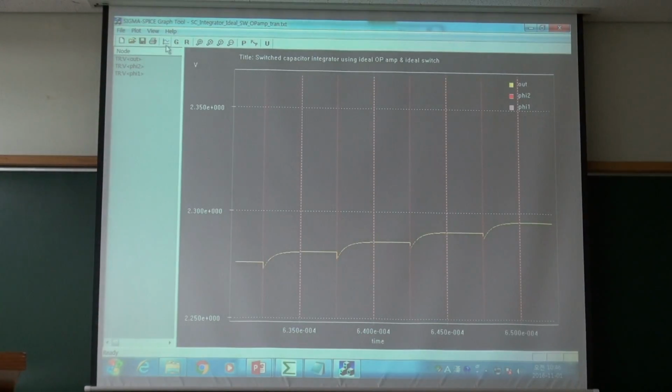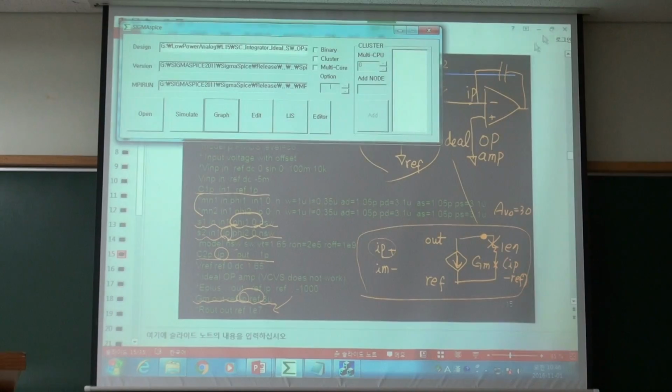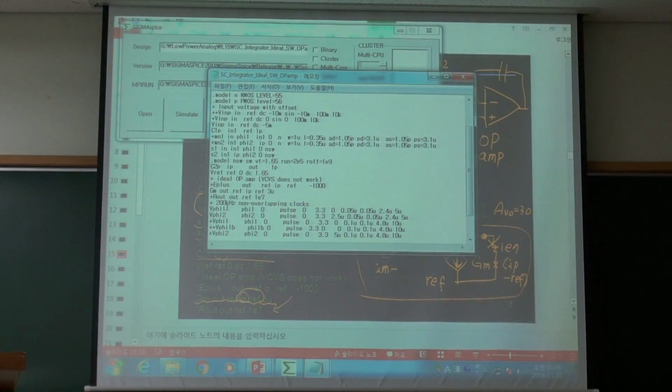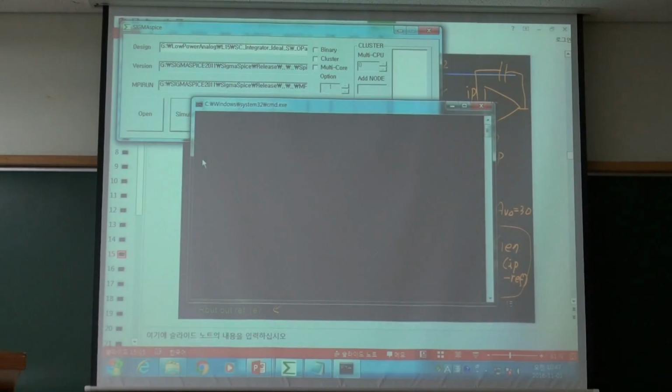Okay, and then let's just see what else. See, if I have some DC resistance here, let's just see R out. Yeah, R out is 10 to the 8. Then my DC gain is this GM times this one, which is 300, okay? My DC gain is 300, not infinite. Then what happens? Simulate.